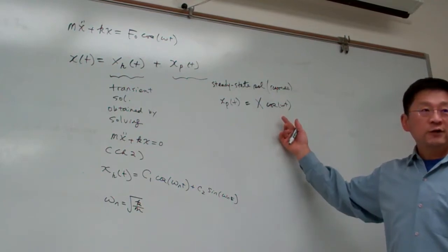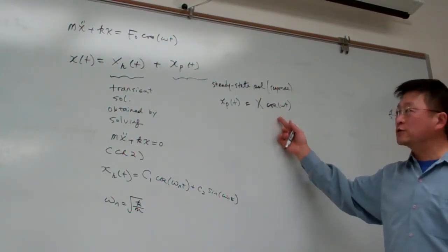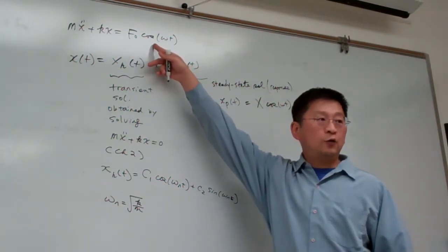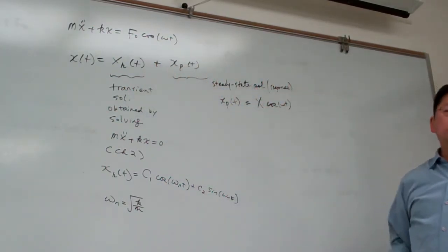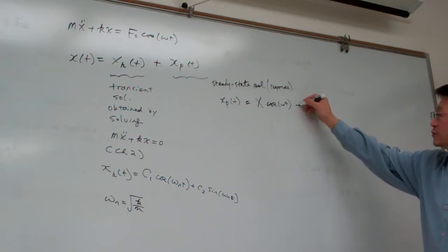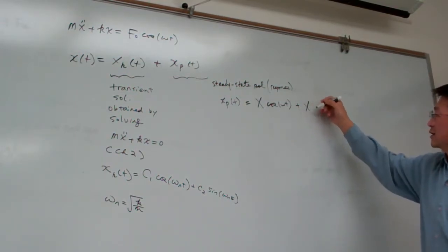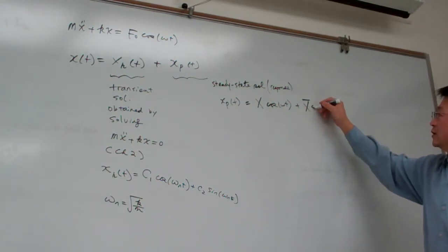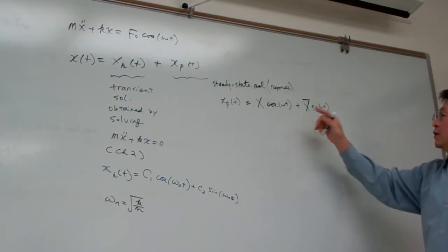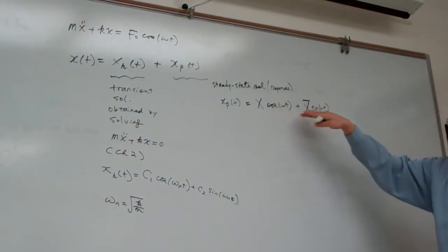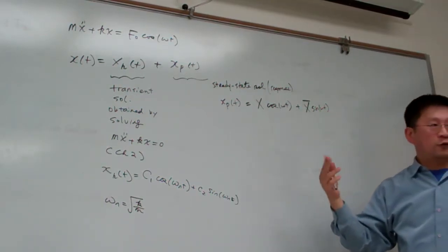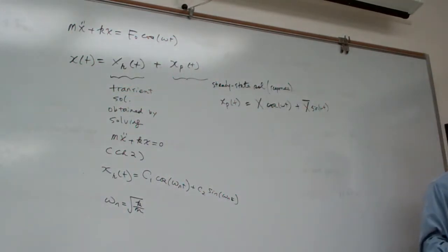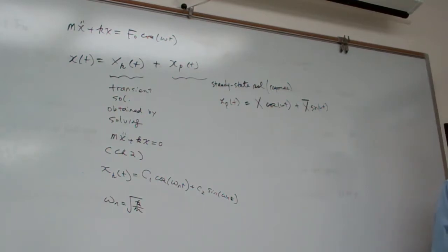And from earlier in chapter 2, from DFEQ, we also learned that any harmonic excitation can appear as cosine or sine. So to make things complete, usually we want to have another assumption, say x bar, another unknown magnitude, multiplied with sine omega t. The combination of cosine and sine makes our assumed form complete, and that will satisfy this. So that is the most general assumption, okay?